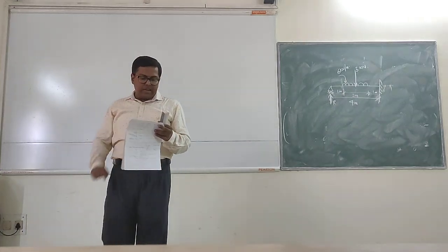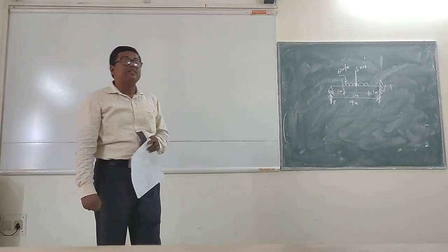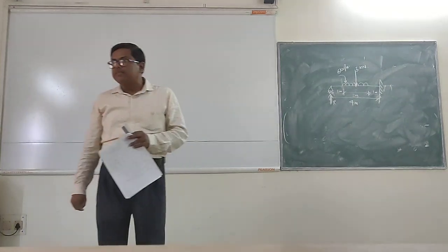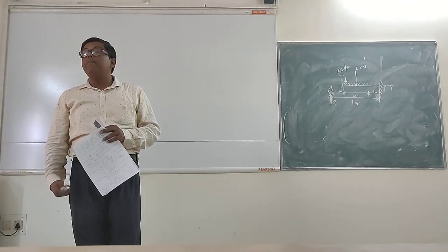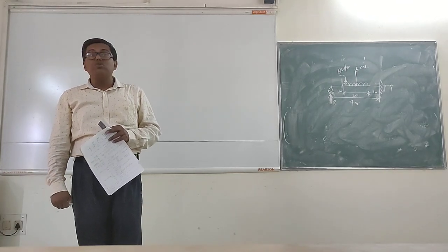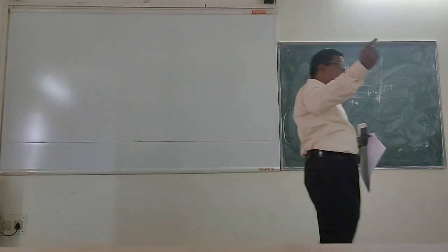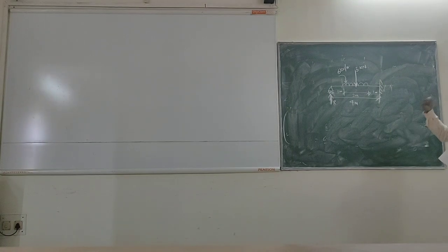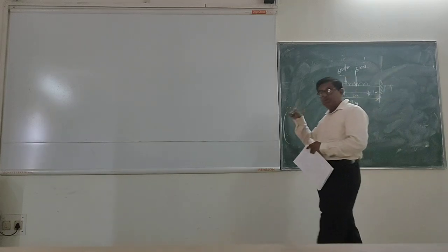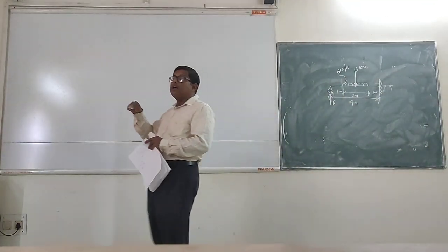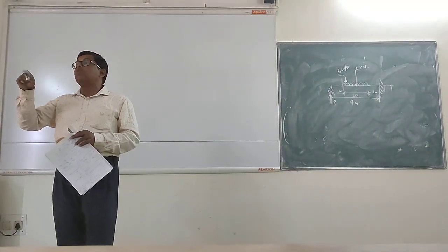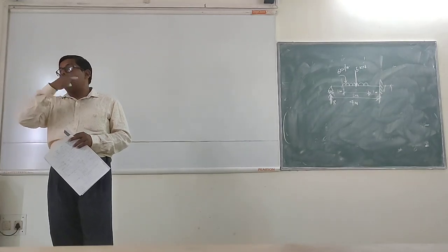And the second question is, find the maximum bending moment in this structure. So basically, if you can find the reaction at the drop end, then you are solving an indeterminate structure. And here we will use the integration method or Macaulay method to solve this problem.